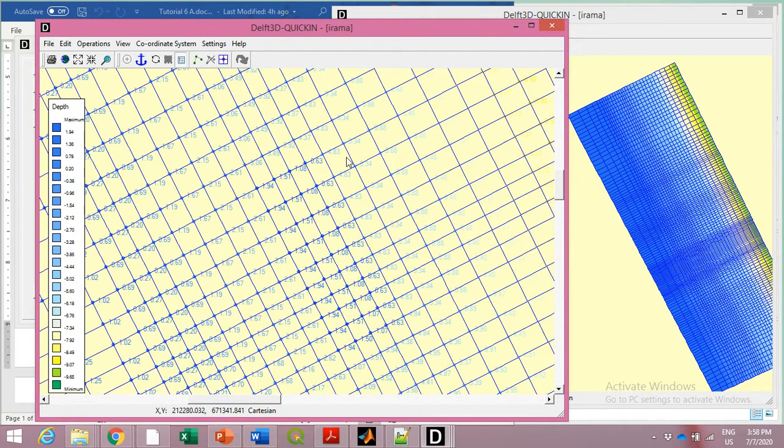So if you notice here, the darker blue is the place where the breakwater is. It doesn't have a similar height, beginning with 0.63 above the mean sea level, then 1.083, 1.51 meter, and 1.94. And it's similar along this line, this line, this line, this line.